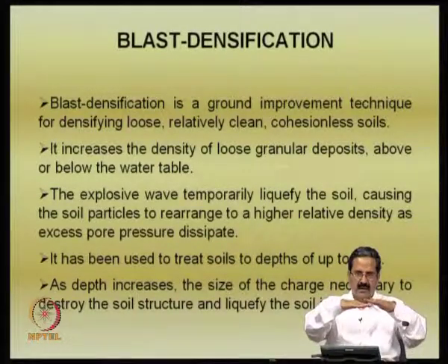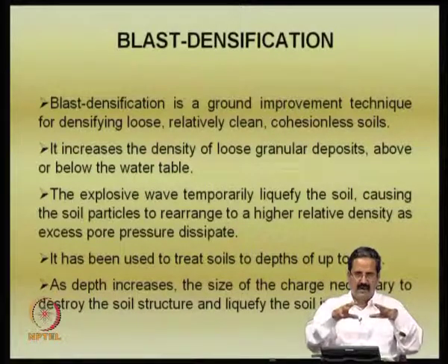Initially the water table and the ground level are the same, but once you vibrate it, the natural ground level goes down. Say, for example, you have 1 meter of sand and 1 meter of water lying above, which means that there is 1 meter of settlement that occurred because of the vibration. So, how do we introduce this vibration?